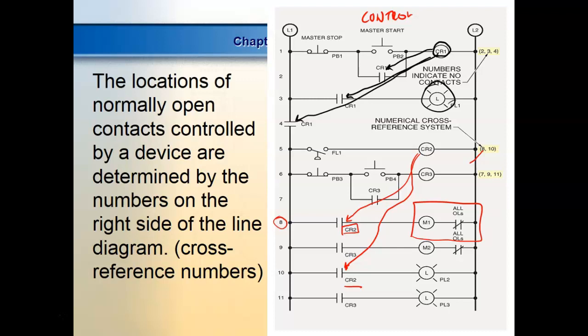And why do they usually split that into two different circuits? The control circuit is usually a low voltage circuit. And what advantage does low voltage have over high voltage? Safer, which means we can get in this thing and troubleshoot it, right? Have no problem. And then these magnetic motor starters won't be in the control circuit. They'll be over there where? Yeah. But this would be what we're talking about, right? You understand that? So most control circuits consist of two parts, a control circuit and a power circuit. So all we know is this guy has no contacts in the control circuit.